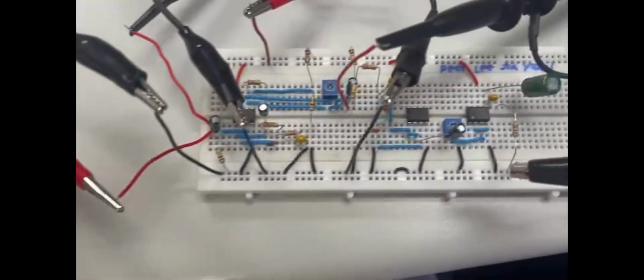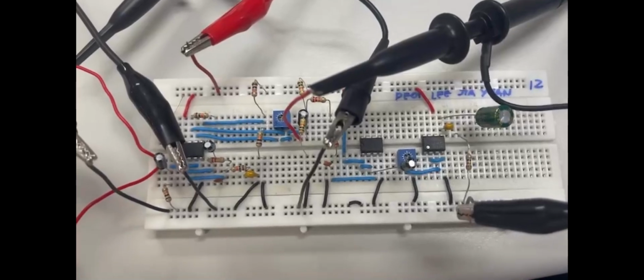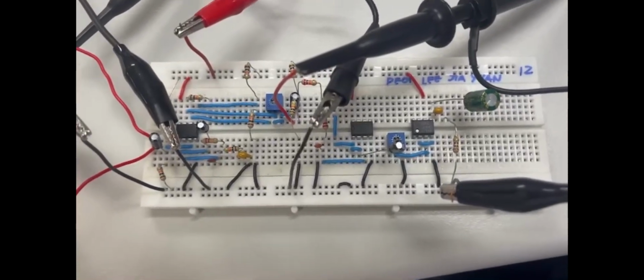To measure TP3, the function generator will be set to 1 kHz and 200 mV peak to peak. It's then connected to our TP1 here. One of our oscilloscope probes is also connected to TP1 to measure input. Then our other oscilloscope probe will be connected to TP3 to measure output. This is shown in the next video clip showing our measurements. For TP3, at 1 kHz 200 mV peak to peak, our voltage output is 5.44 volts.